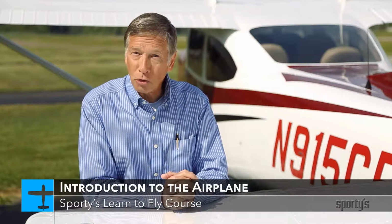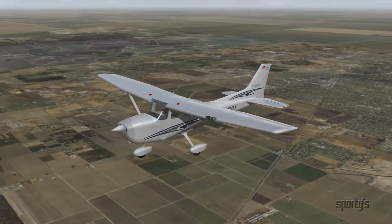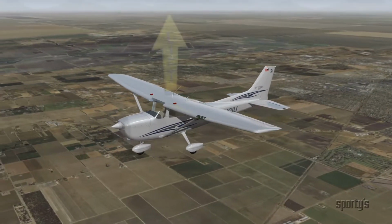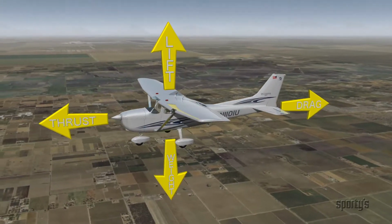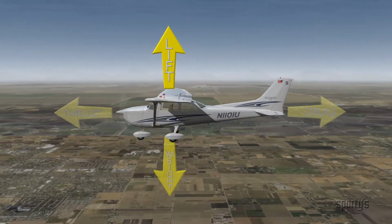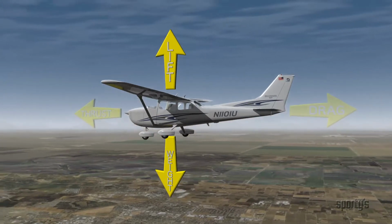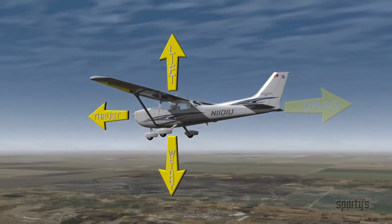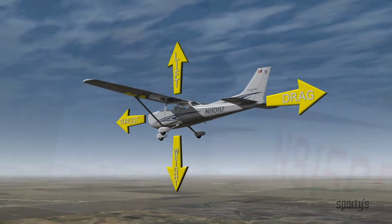Let's take an introductory look at the airplane, its controls, and the aerodynamics that make it fly. The four forces which act on an airplane in flight are lift, weight, thrust, and drag. Lift is the force that acts upward against weight, which is caused by gravity. Thrust propels the airplane forward, and drag acts opposite of thrust.